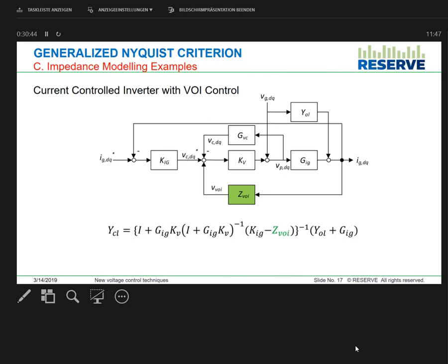That's how the inverter is behaving now. So if I want to slow down the rate at which the inverter should inject current, or speed up or increase the bandwidth, in other words, then I can just play with this and make sure that this entire term has a certain bandwidth, because this is representing how the capacitor voltage reference is going to the inner controllers.